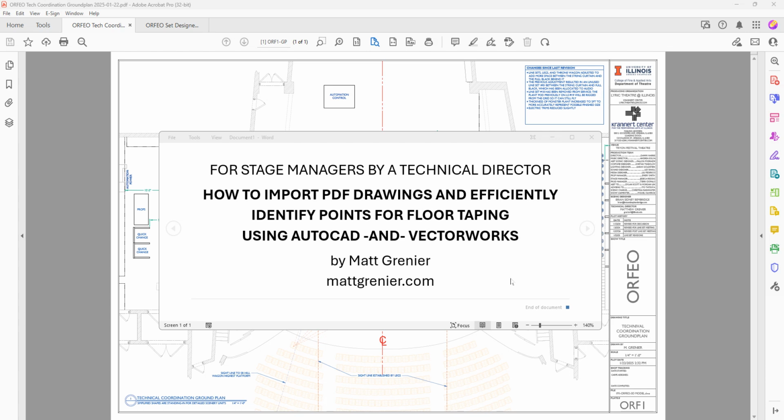I'm also not going to go over how to produce your own drawings with coordinate points added. The purpose of this is to bring a drawing into AutoCAD, whether it's a PDF or an image file, and scale it, get it at 0, 0 on the origin, and then take points, determining coordinates efficiently so that you can then write them down on a printed drawing that you already have, or annotate them on a separate PDF, however you want to document them.